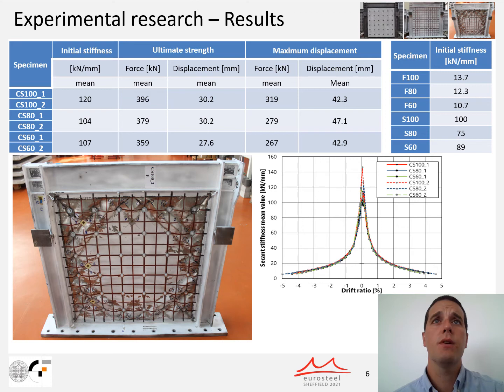Failure of composite specimens started due to exceedance of the bearing resistance of the steel infill plate at a connection with the reinforced concrete panel. Although this failure mode was taken into account in the design process, it seems that the prescribed approach is not valid for composite plate shear walls that have a gap between the reinforced concrete panel and boundary elements. Such a failure mode is not desirable for a couple of reasons.